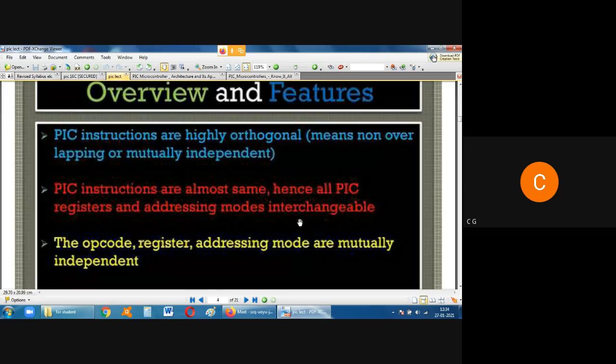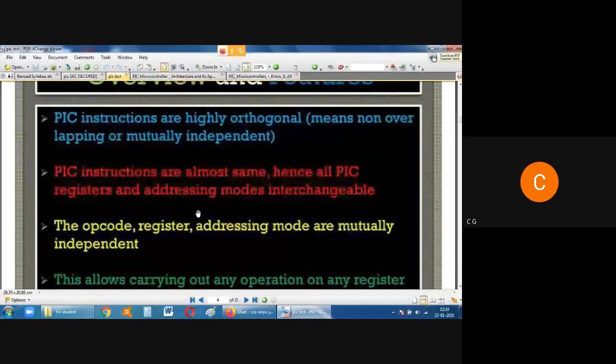Otherwise, what you would have to do is first store the content of the register, meaning the answer of the multiplication. Then you have to transfer the count which you placed in register C, that has become 0. Okay, this is the cross checking. So you have to transfer the content of register C to register A, then from register A it will go to the memory. That kind of operation is avoided, and thereby you save the time of the multiplication process or other things.